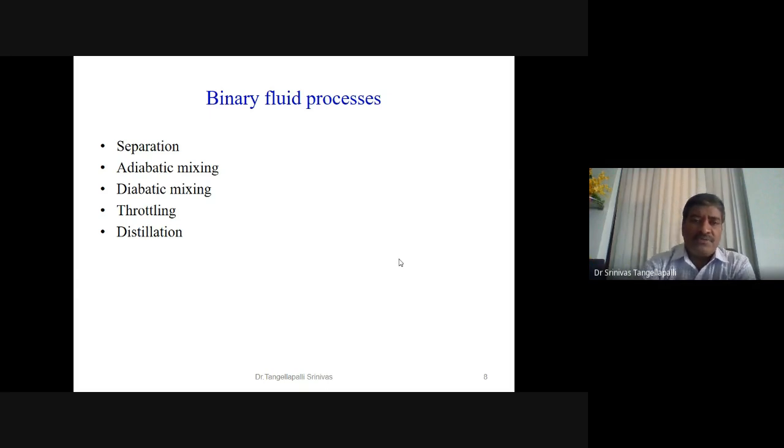ammonia water mixture can be used for three applications: cooling purpose, power generation purpose, and third is combined cooling and simultaneous power generation. That's why this fluid has great flexibility, but with some limitations, like at the domestic level it's difficult to use the ammonia because it is toxic, it has a smell, and once we inhale it, the lungs are affected, respiratory system problems will come. That's why this mixture is not advisable for domestic applications.